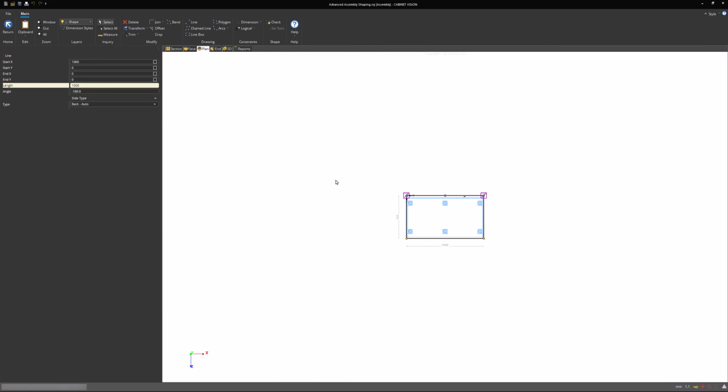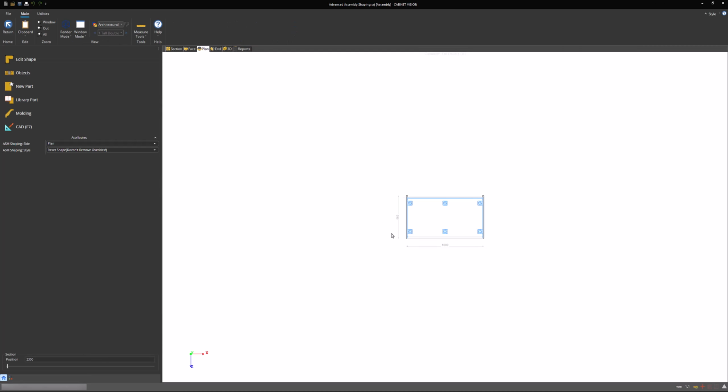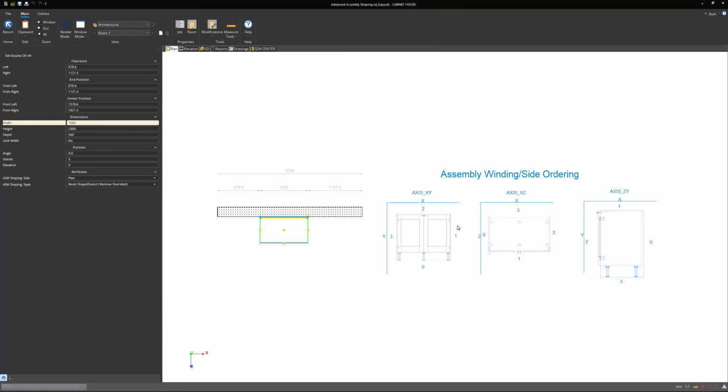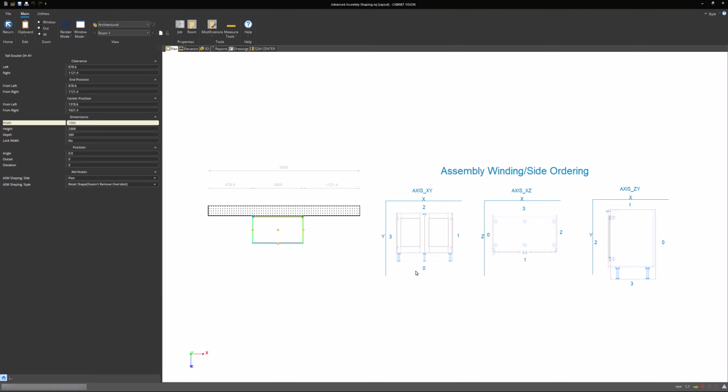Just one other thing to mention, and I've mentioned it in previous videos, but I'll say it again. When we're creating the shape of an assembly, it's important that we follow the correct order that the assembly is drawn. I'm highlighting this again because when I originally put the UCSs together, I didn't work this out, and I drew some shapes and had to rewrite a lot of the logic that was in there originally. So when we're redrawing an assembly shape, we follow the correct order of the sides. It's also important that when we're resetting the sides, we follow the same order as well.